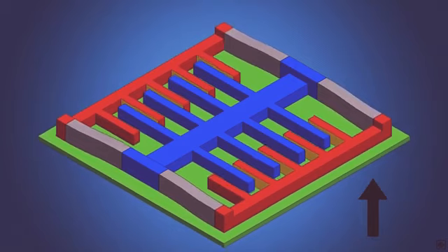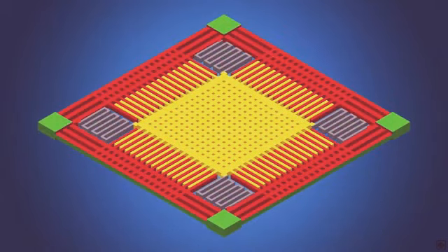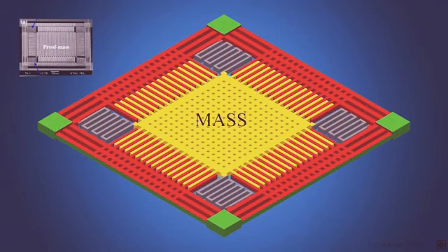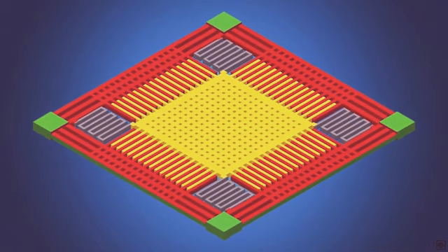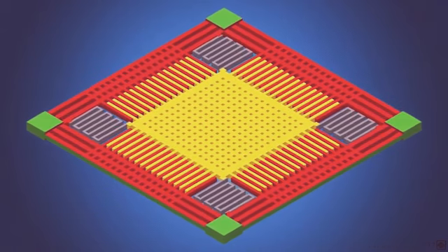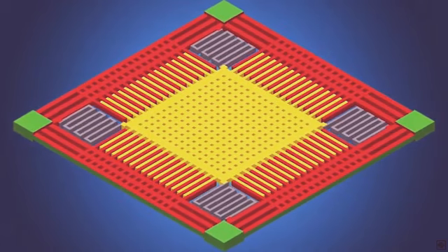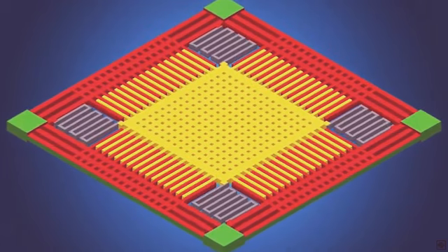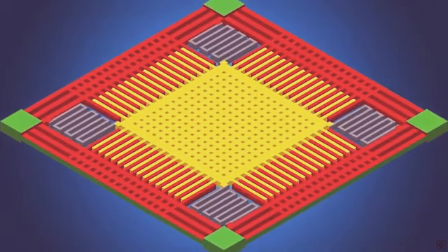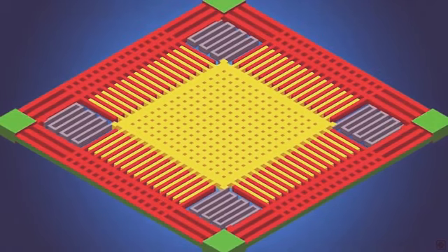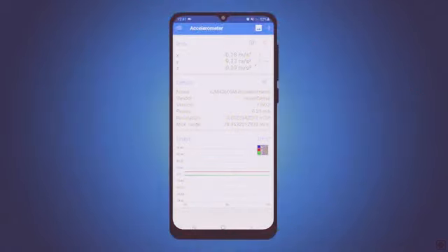This accelerometer can be modified to sense motion in all three axes. In this configuration, the proof mass is suspended in the center of the frame with the help of microscopic springs. Acceleration in the XY plane is sensed by capacitive fingers fixed on the frame of each respective axis. Both sensing structures also contain electrodes that can sense vertical travel of the proof mass, forming the Z-axis accelerometer. Now we can sense which way is down precisely.